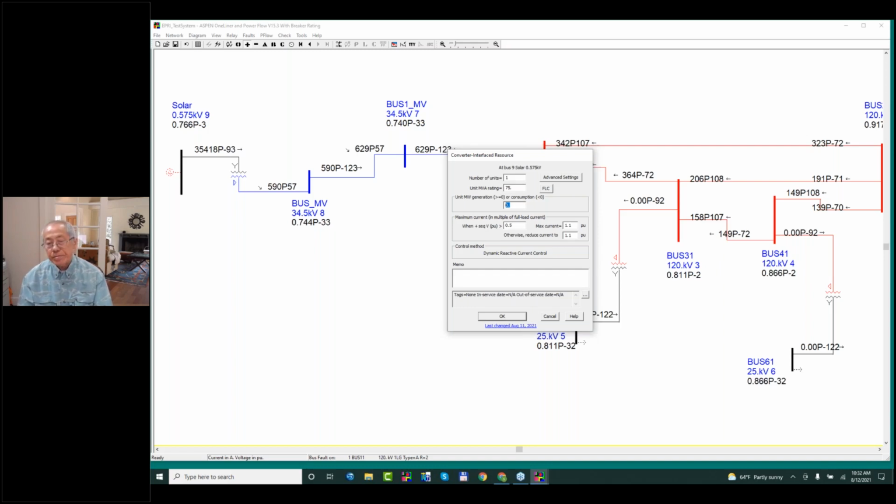And also in a couple of really big networks, I have found that this affects the convergence of these gadgets altogether, because you have a completely unrealistic system when you have these things putting out megawatts and there's nothing to absorb it. They all ended up at the slack bus one way or another. I mean, we don't have a slack bus in this system, so they all ended up at the synchronous machines.